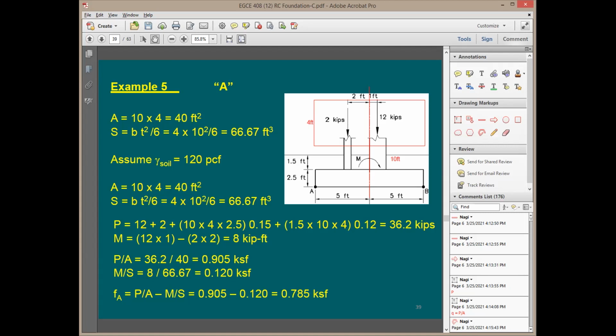Do you guys remember the confinement of concrete? You remember anything about this confinement thing, or no? Yeah, the spiral is more confined. So what does the circular column confinement do to the confined concrete? Is it bringing a better column or better concrete, or lower in quality?